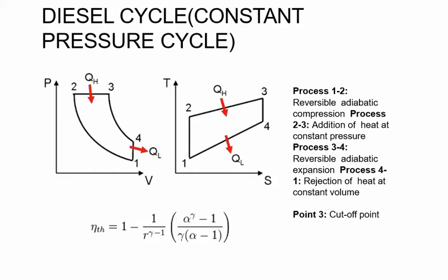In this, the fuel is ignited by heat generated during the compression of air in the combustion chamber, into which the fuel is then injected. This is in contrast to igniting the fuel-air mixture with a spark plug, as in the Otto cycle engine.